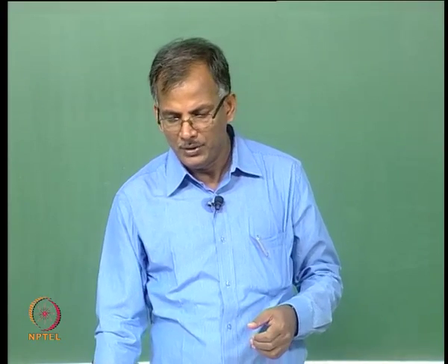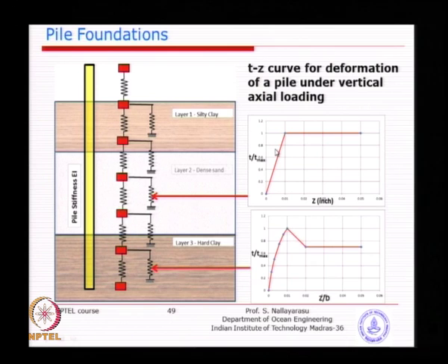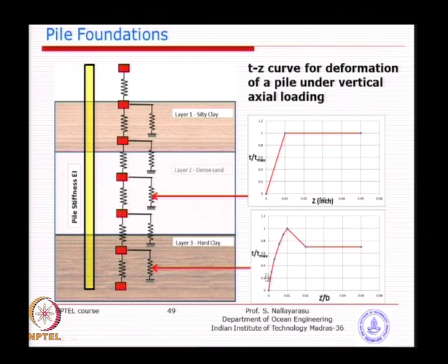That's why many times if you are able to get a linearized thing, then you don't need to worry about it, because it becomes simplified, because you will be using only one single spring value, whereas here you got multiple values, because every time you take a tangent you will get a slope, you take another tangent you will get another slope. So every time your spring value changes depending on what your displacement is.